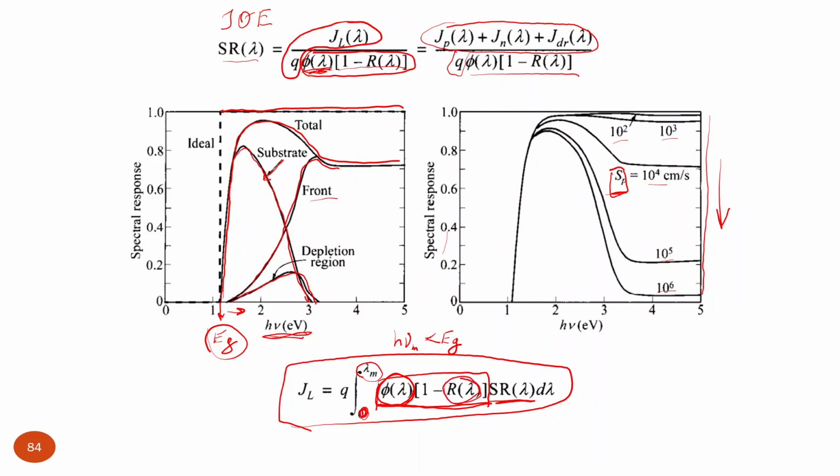We can reduce this reflection by anti-reflection coating, and for spectral response, quantum efficiency, we need to design the solar cell first of all with appropriate material, high quality, with reduced recombination losses, and increased extraction of photogenerated charge carriers, and that will help us increase this parameter. So if we increase spectral response and decrease reflectance, keeping this constant, we can increase the photocurrent of the solar cell.